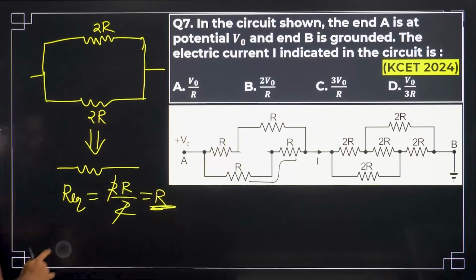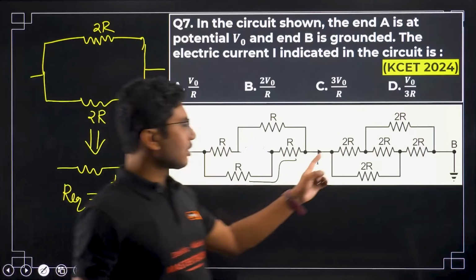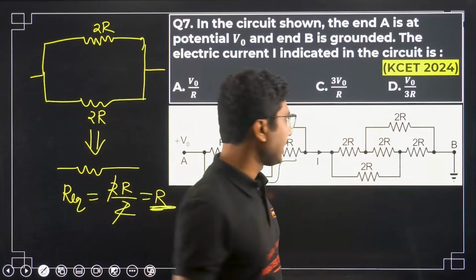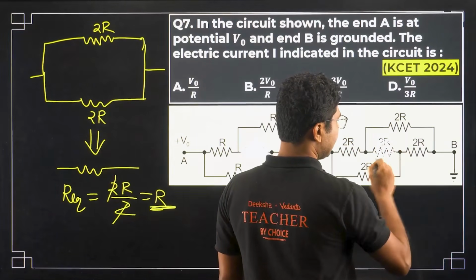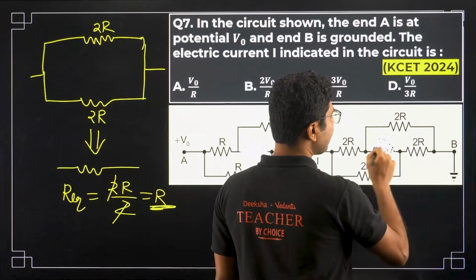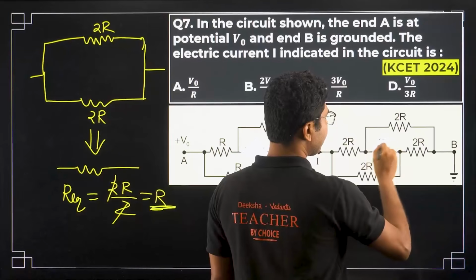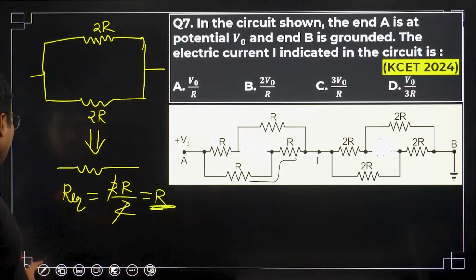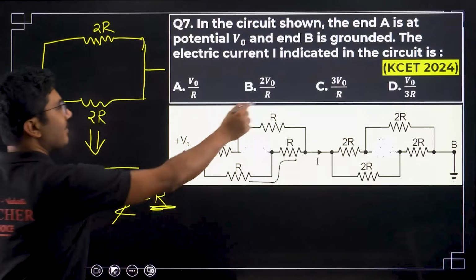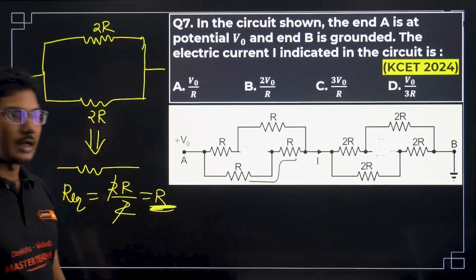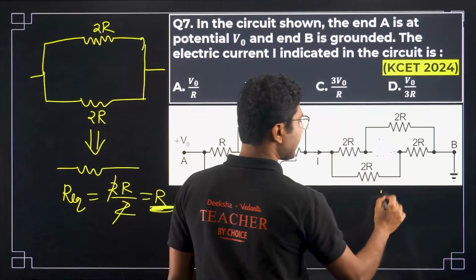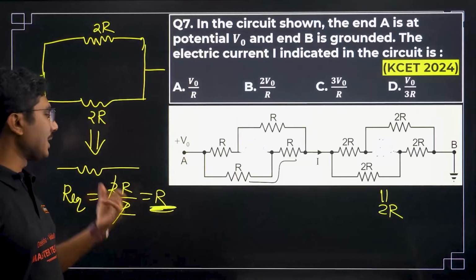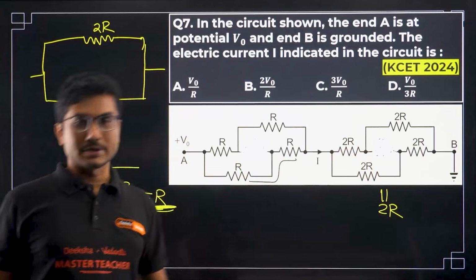their equivalent resistance is also R, correct? Now, here also you will see that this is another Wheatstone bridge, 2R, 2R, 2R, 2R, right? So, again we can ignore the central resistance in this part as well. This is the second Wheatstone bridge, so we just need to ignore its central resistance. Again we will get a similar structure. From the similarity, if everything is R, the equivalent resistance becomes R. So, if everything is 2R, the equivalent resistance will be 2R, right? We don't need to do the mathematics once more because we have done it once. That means the second one also we can simplify easily.